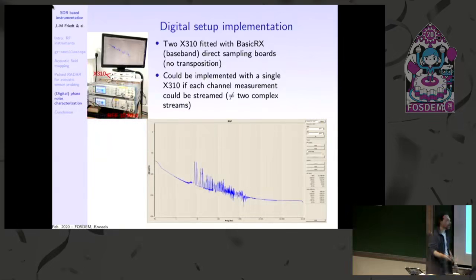And what I would like to emphasize is all these spikes here. We did a presentation last year at the International Frequency Control Symposium. If you look at the Rohde & Schwarz system, they will hide all of these for you. Whatever these spikes are, they consider them noise, and they will just smooth them for you. Actually, Rohde & Schwarz is not that bad because they have a mode in which they still give you the raw data, but the displayed data has been smoothed. So you always see these very beautiful charts, but phase noise always has this spurious information.